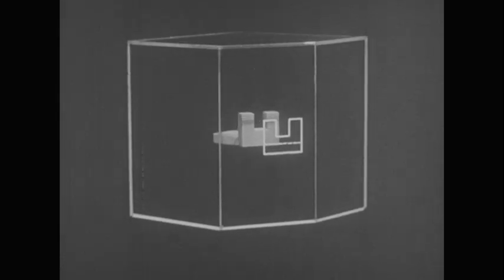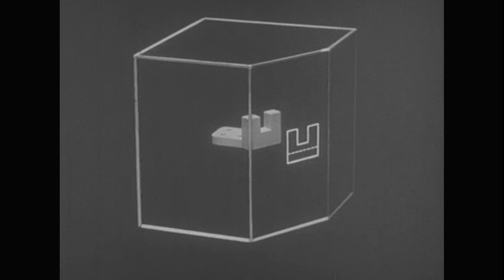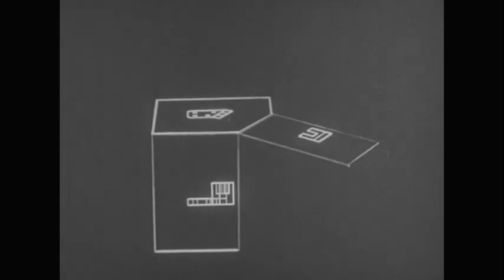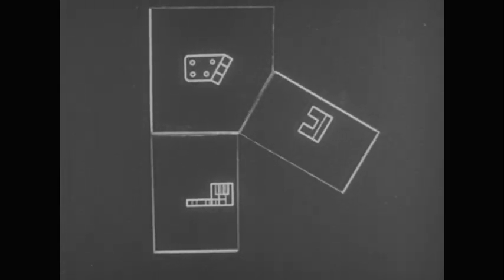There is nothing complicated about auxiliary views. You simply put the projection plane parallel to the slanting face of the object. The auxiliary view and the top and front views, or as much of them as you need, describe the object completely. The side view is unnecessary in this case. The position of the auxiliary view on the drawing paper will be decided by the position of the auxiliary plane in relation to the principal planes.